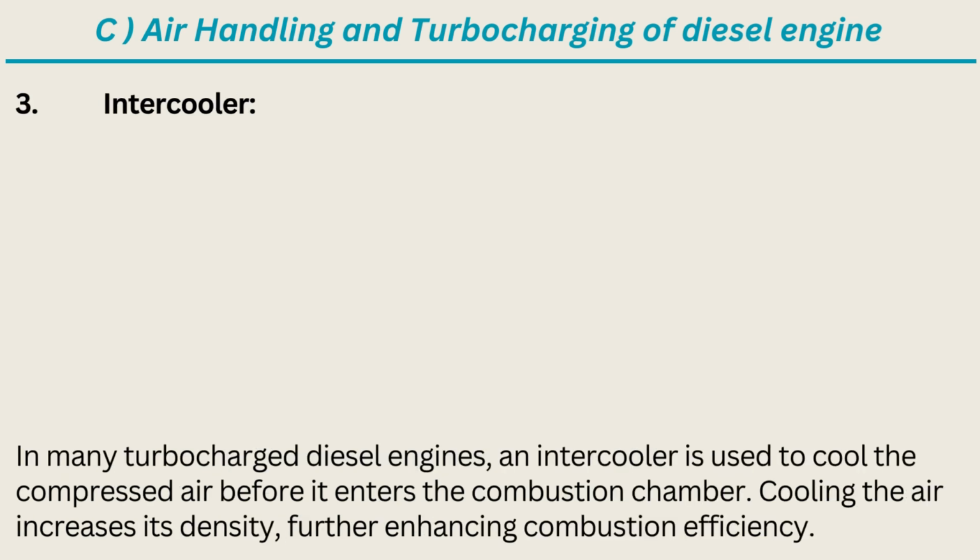3. Intercooler. In many turbocharged diesel engines, an intercooler is used to cool the compressed air before it enters the combustion chamber. Cooling the air increases its density, further enhancing combustion efficiency.